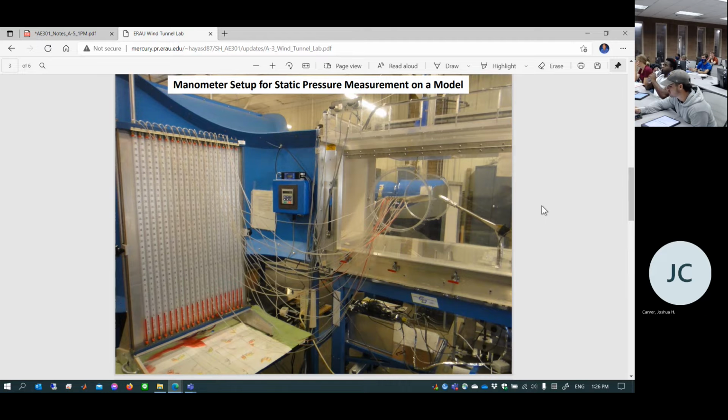Now, suppose this is attached to some other device, something called a balance system, that actually measures the force created in a certain direction, parallel and perpendicular to the chord of your test model. So one is a direct measurement of force. The other is a pressure distribution measurement, and then you can resolve it into force components later. Then you can compare those two. Okay?